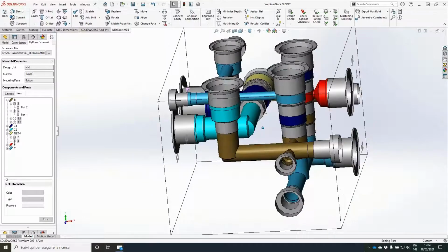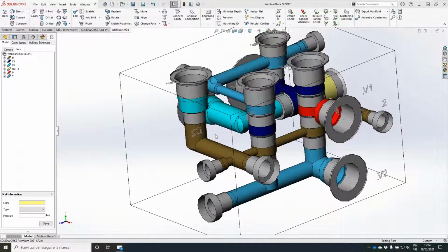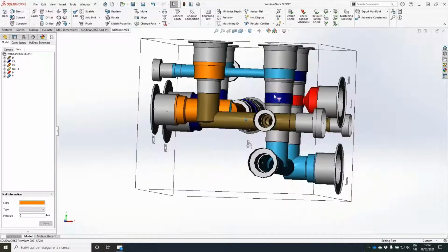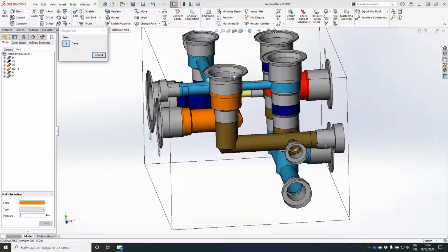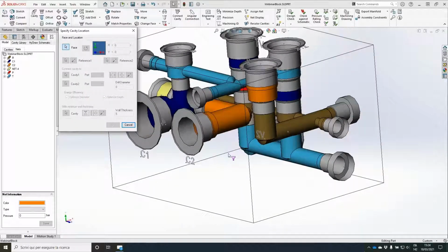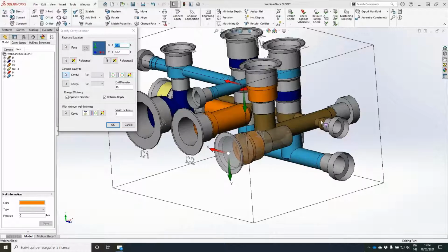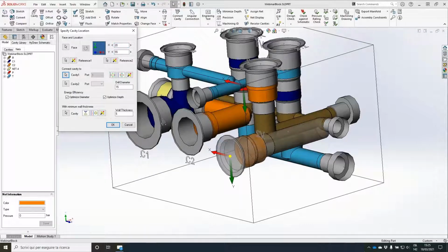In order to help visualize the connections needed, let me go back to the net. And I want to change the color of the net C2. Let me change the color and take an orange. So now this will be easier to identify. So I need to connect those cavities. And basically, a smarter idea would be just to change phase, if doable, of course, depending on the constraints of the design. But we could say we put this cavity here, we connect directly to that plug, and later we will remove the back construction plug. Let's select position 20, 55. That is fine.